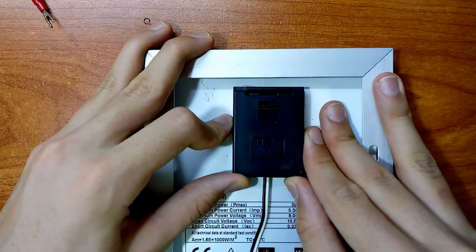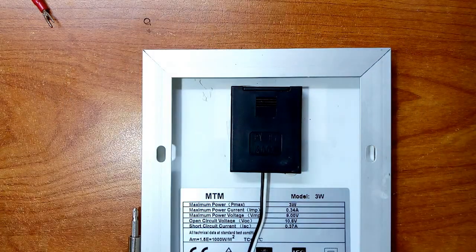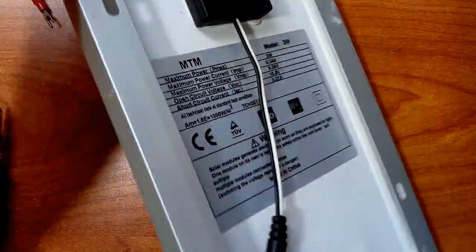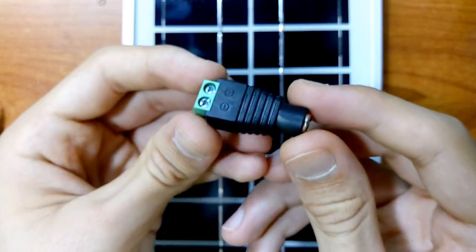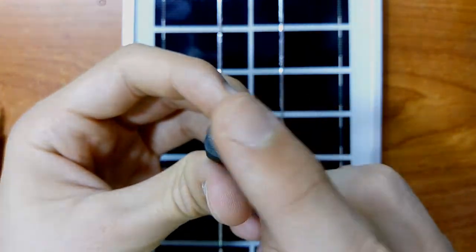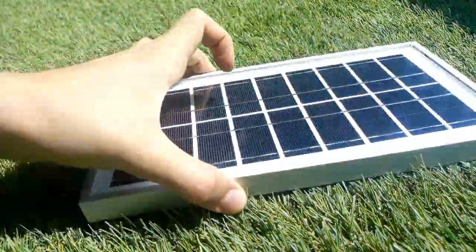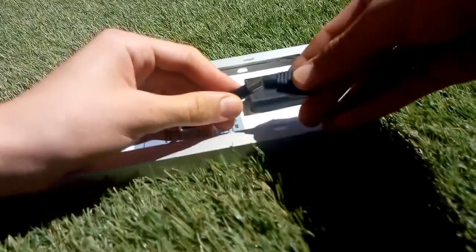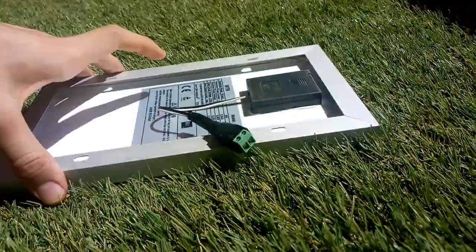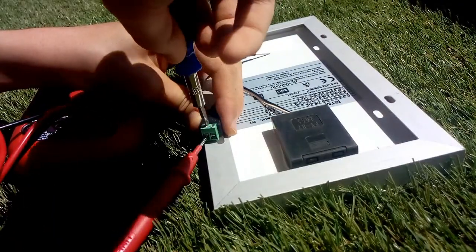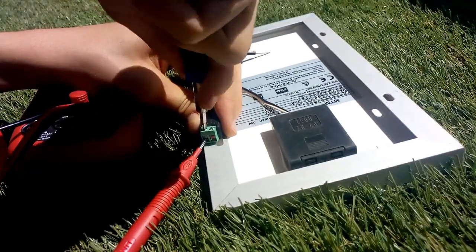I have a small converter that converts the DC male wire into a terminal block, so I can screw any wires or anything to measure the voltage, for example. Now I will go outside in the morning, it's around 9 o'clock, and I'll be doing some measurements. Now I will get the connector and connect it to the solar panel, and also I will get my digital multimeter and put it in the voltage reading mode, and I will just put the probes of the digital multimeter into the terminals directly and just screw it. So it's a nice solution.